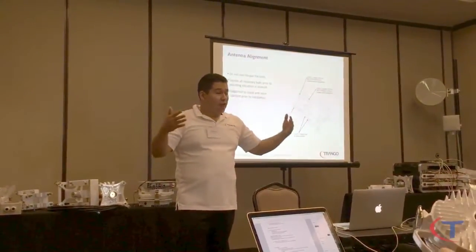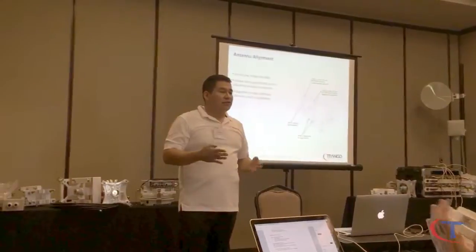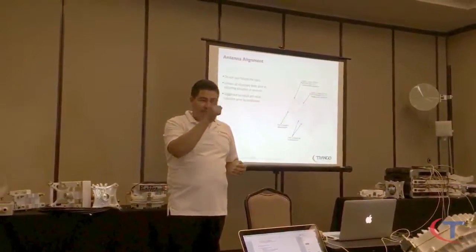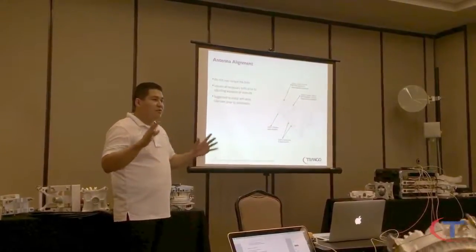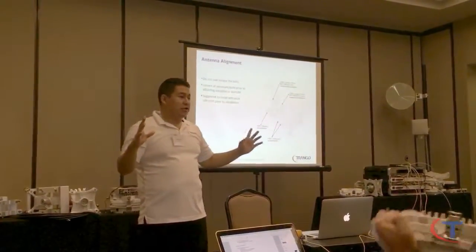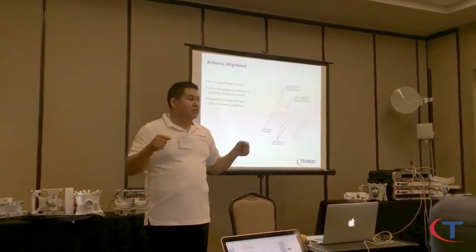If it moves around, you're going to see your RSSI do what? Symmetrically go up and down. Exactly. And it happens, right? So just make sure if it's a 4-footer or 6-footer dish, you have the right struts on the tower.